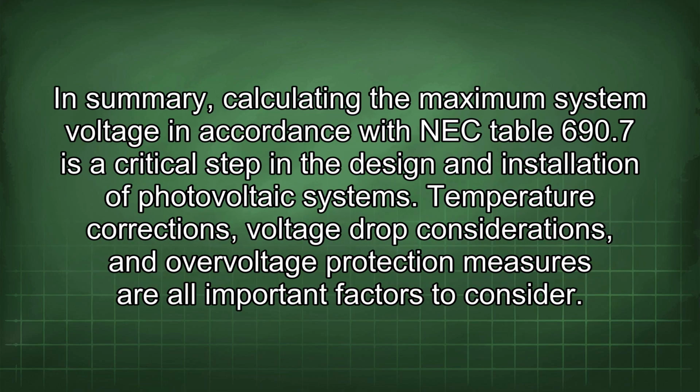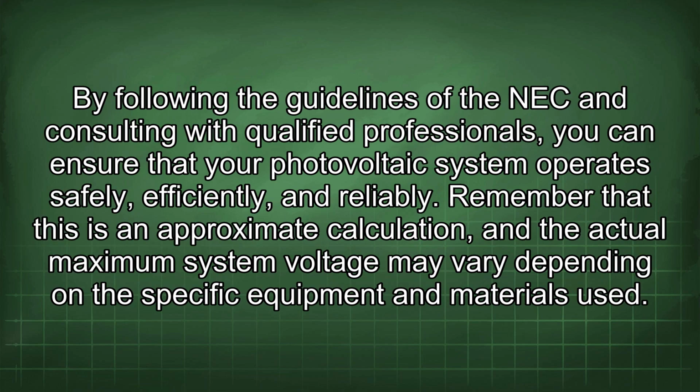In summary, calculating the maximum system voltage in accordance with NEC Table 690.7 is a critical step in the design and installation of photovoltaic systems. Temperature corrections, voltage drop considerations, and overvoltage protection measures are all important factors to consider. By following the guidelines of the NEC and consulting with qualified professionals, you can ensure that your photovoltaic system operates safely, efficiently, and reliably.